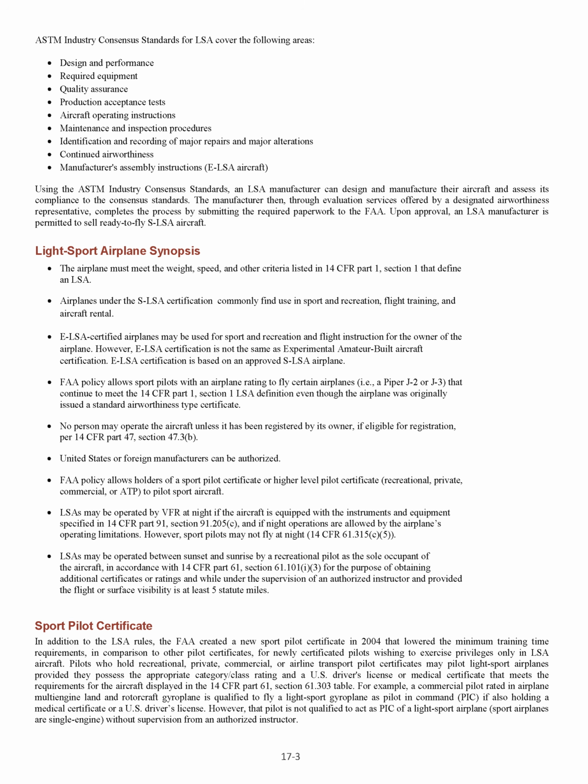Light sport airplane synopsis. The airplane must meet the weight, speed, and other criteria listed in 14 CFR Part 1, Section 1.1 that define an LSA. Airplanes under the SLSA certification commonly find use in sport and recreation, flight training, and aircraft rental. ELSA certified airplanes may be used for sport and recreation and flight instruction for the owner of the airplane. However, ELSA certification is not the same as experimental amateur-built aircraft certification. ELSA certification is based on an approved LSA airplane.